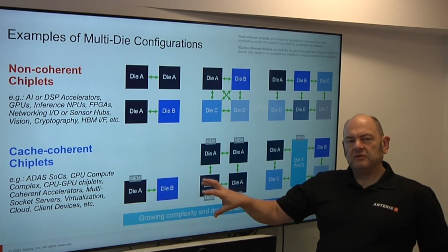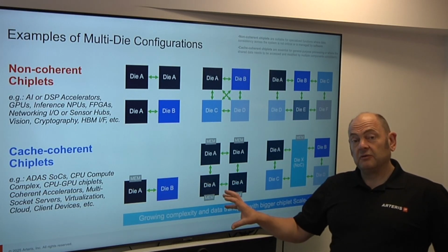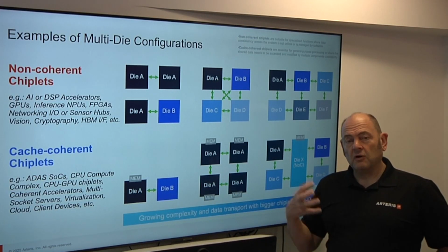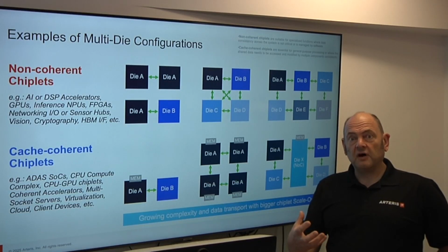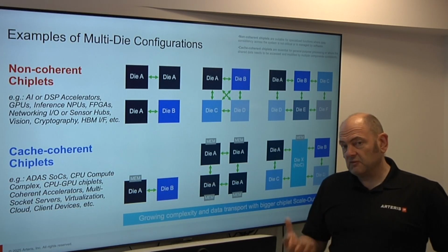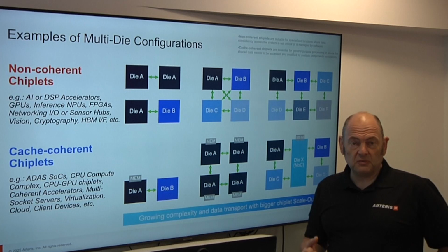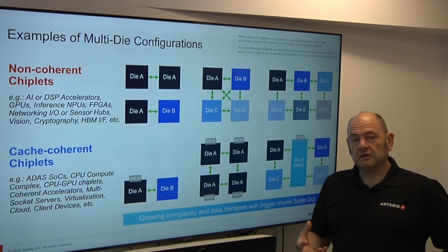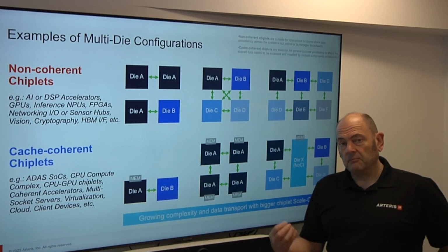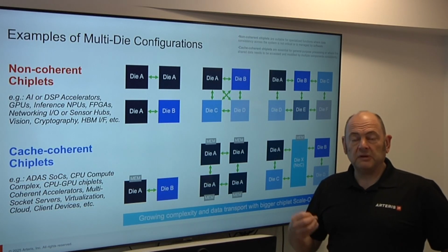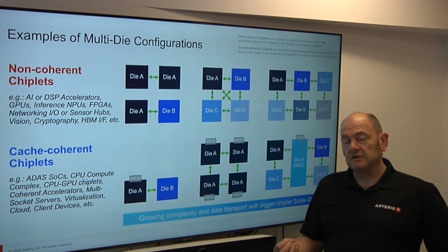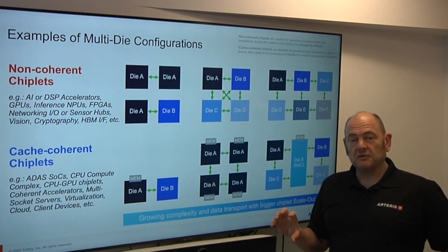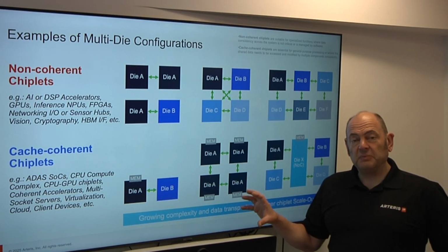The reason that we'd actually disaggregate or scale out and have an accelerator separate from a CPU cluster is that we can keep the CPU cluster on a current or an advanced process node, taking advantage of the low power that that gives you, say 2-3 nanometer nodes. On the accelerator, especially if it's got a specific task or it's SRAM based, for example, or even has some high voltage IOs on it, that can be used in a slightly earlier process node that's basically mature but specific for that task.